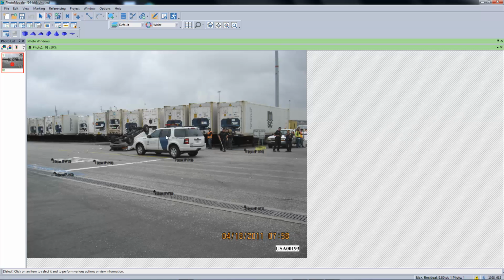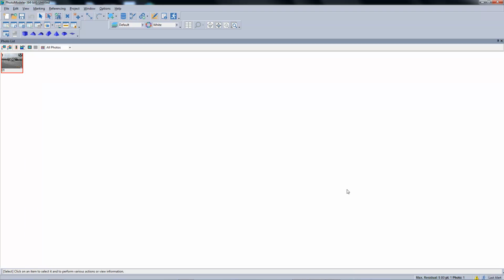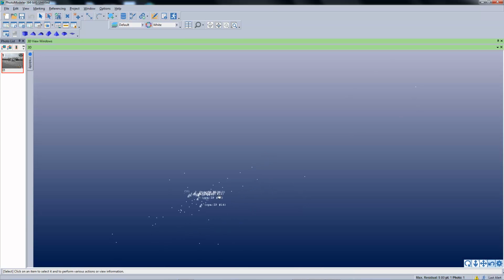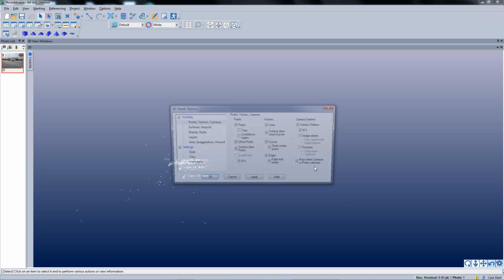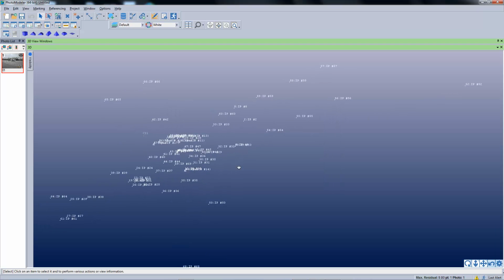So that's what we're going to do. We're going to define a surface that's underneath this yaw mark, and then we're just basically going to trace that yaw mark on that surface, and we'll be done. So I generally like to do this in the 3D viewer, and here I will turn on the imported point IDs, and the imported points, of course, are the total station data.